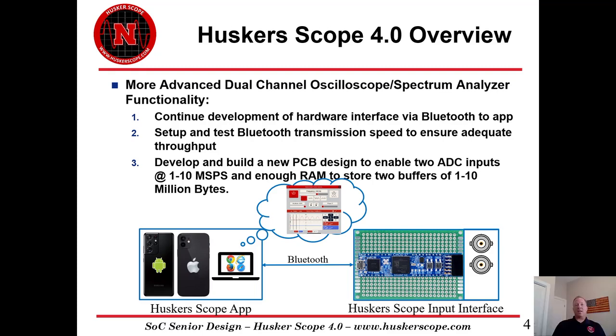We're also going to be developing a new PCB design to enable those two ADC inputs through the BNC connectors at 1 to 10 million samples per second and enough RAM to store two buffers of 1 million to 10 million bytes each.